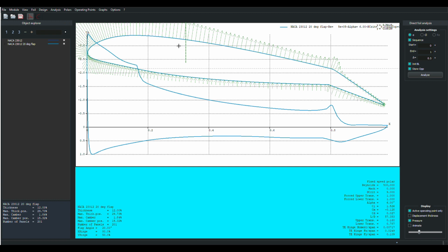However, it's not plausible to hinge the elevon at the spar along the entire length of the elevon. It'd be so heavy, and you have flutter problems, and you can't counterbalance. It just goes on and on and on.